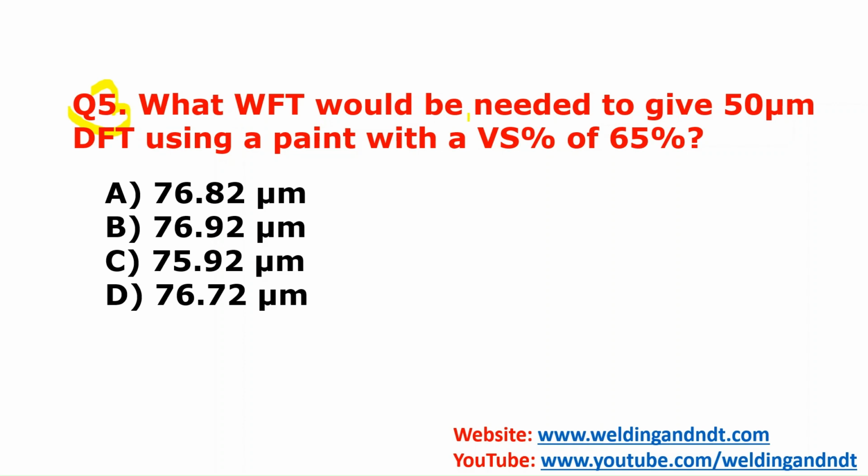Now what WFT would be needed to give 50 micrometer or 50 microns DFT using a paint with VS 65%. So volume solid is 65% and to give 50 DFT. DFT is 50 microns. So you have to calculate the WFT.